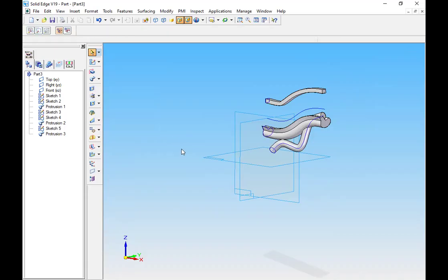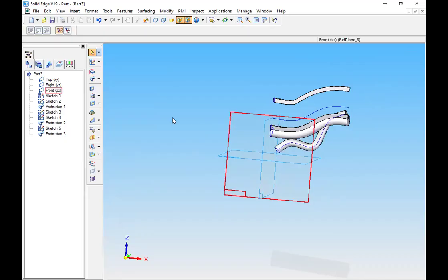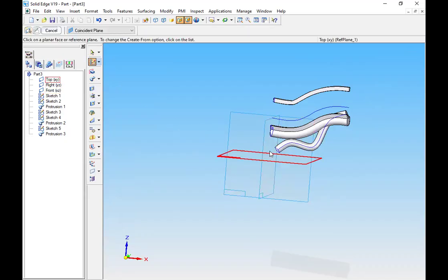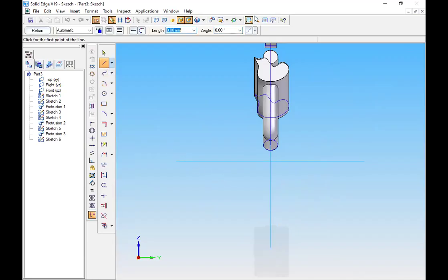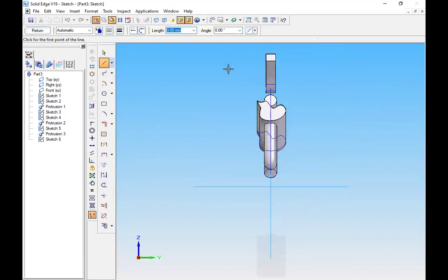So what I will do, the path will be the same. I'll take up sketch, sketching plane as this one. Okay. Same path, we will not change any path. I'll take up circle, because within this profile we should have a cutout. If you draw the cutout somewhere else, we cannot do the cut. We should have material to cut, meaning I have to select the already protruded part.